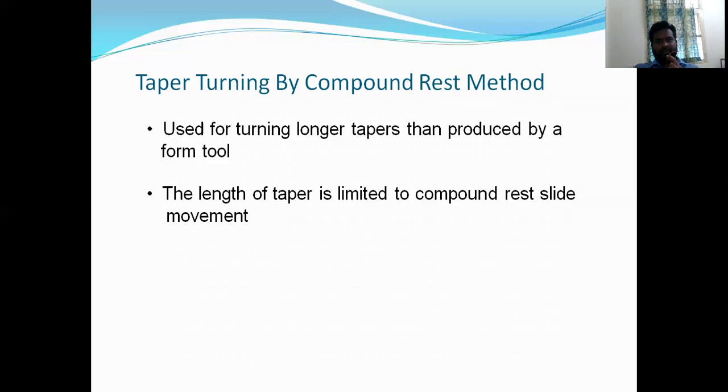The length of taper is limited to the compound rest slide movement. Here in the compound rest method we have one drawback. In the forming tool method, the length of the taper is limited to the width of the cutting tool.